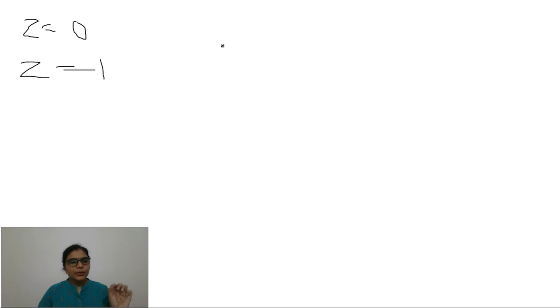The zero flag always denotes the zero result. The zero flag can be set to 0 or can be set to 1. If the zero flag is holding the 0 value, it denotes a non-zero value of the result. If the zero flag is holding bit 1, it denotes that the result was 0.